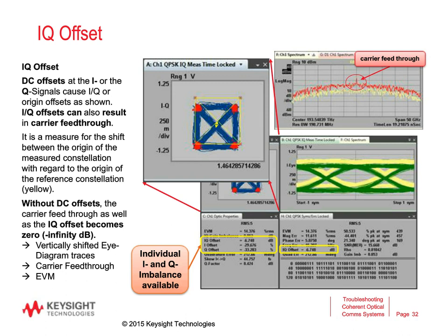Again, we show the yellow reference, and you see the blue constellation is slightly shifted towards the 6 or 7 o'clock position on the screen. And again, the optical modulation analyzer software shows the IQ imbalances and IQ offsets also for the complete signal as well as for the individual contributors for I and Q. And if we would have 0 DC offsets, the IQ offset will become 0. So that means I'm seeing a minus infinite dB value reported.